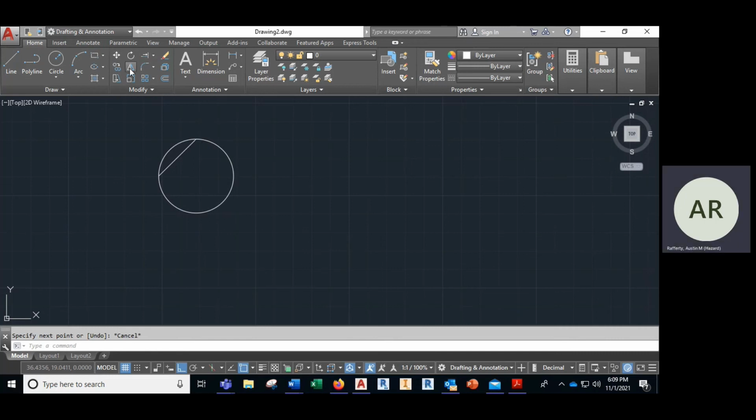All right, now we're going to mirror. So there are two mirror lines here. There is a horizontal and a vertical, and both of those are connected to our right and our bottom quadrants. So the way we're going to do that, we're going to go to mirror, select the objects. My object is right here, both lines. Should have two objects found. And I'm going to hit enter.